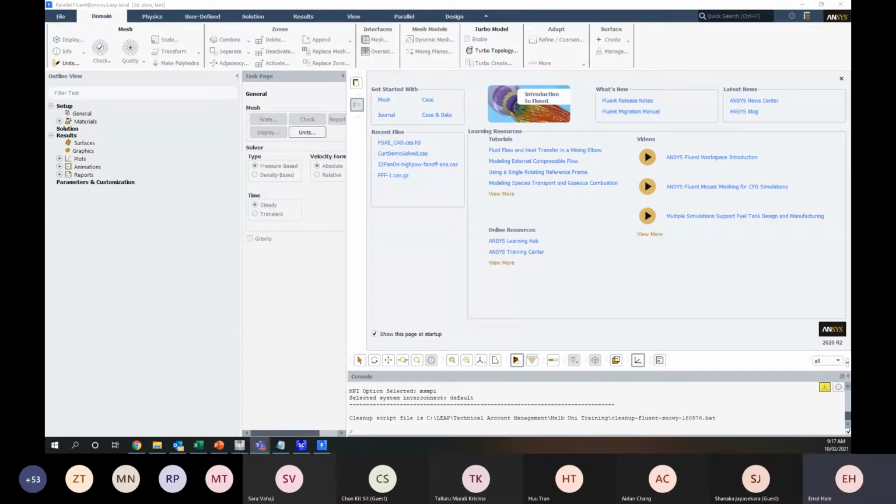So a couple of questions I haven't addressed. What angular resolution do you recommend for a production run? Meshing is a really difficult one to provide any hard recommendations. One of the most important things you need to do in CFD is to always be conducting mesh independence studies. So if there's ever a concern about exactly what angle or what mesh size to run with, we can always start with the defaults, set up and run our solution, and then come back to the meshing and change some of those values to make sure we're getting a different mesh.